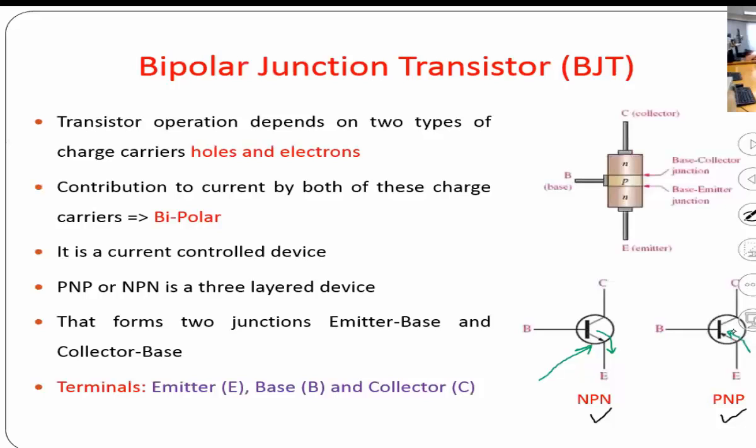So all you do is, it's three terminals just like this. It's up to you whether you put a circle or not. It doesn't really matter. So this is the transistor. If you see the arrow pointing out, that means it's an NPN type of transistor. Current is leaving. So this tells you whatever this terminal is, the current is leaving the terminal for NPN. For PNP, the current is entering for the same terminal.